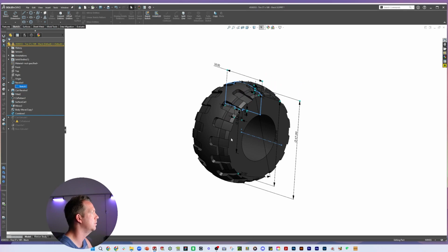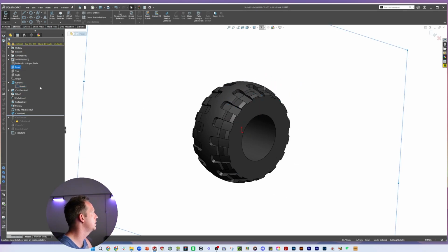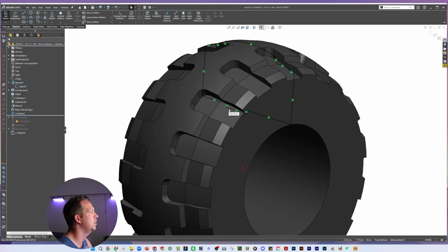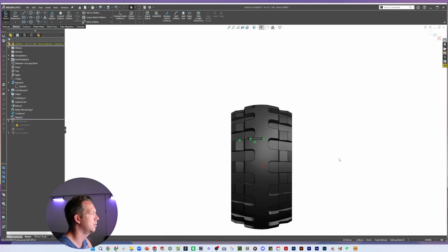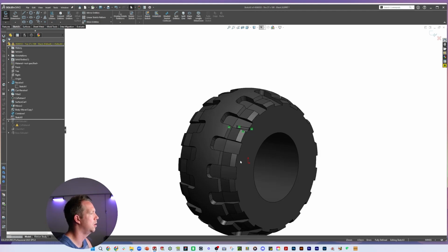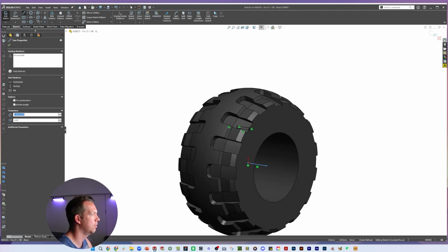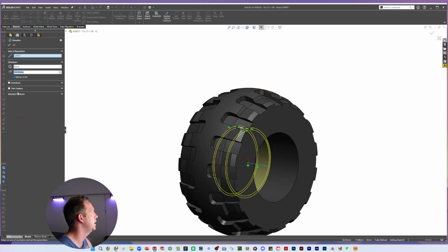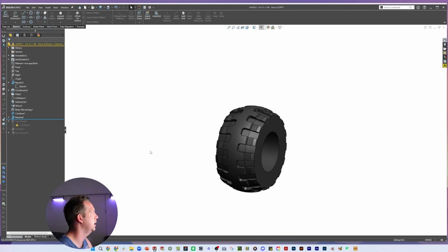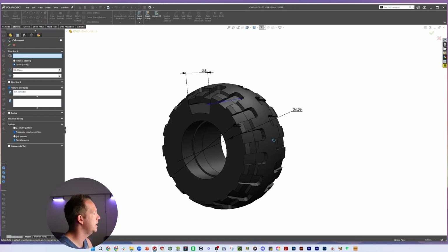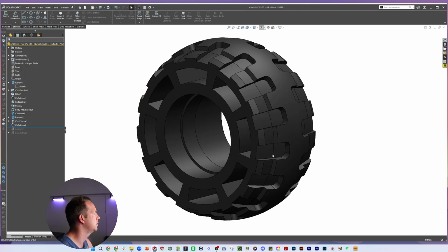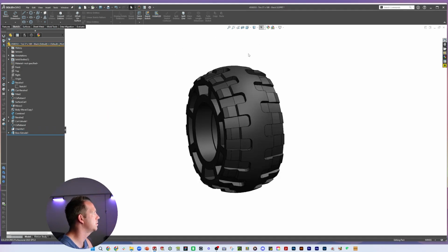So when we cut it and put it back in, we've lost that revolve, that little section in the middle. So what we'll do is a new sketch on the front plane. We'll convert that sketch. I'm going to delete all of those elements and replace that one. I'll put a construction line in the middle to revolve around. And then I'm going to revolve that. Let's put that little bit of thickness back in. Now my circular pattern, I can once again pattern around any edge. I didn't need it there, but I can just update that. Put the chamfer back in and my boss extrude at the end.